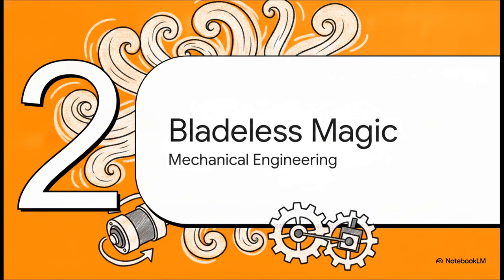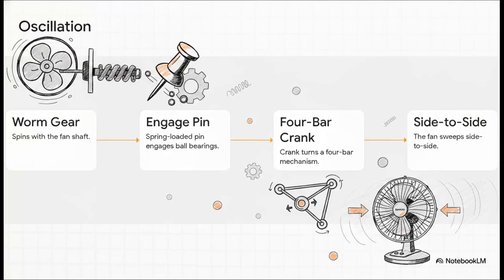Moving right along to Section 2, Bladeless and Oscillating Magic, uncovering clever mechanical engineering. Okay, have you ever wondered how pushing down that one tiny pin on top of a fan suddenly makes it look left and right? It's like a mini mystery. Inside the gearbox, the fast-spinning fan shaft turns a worm gear. When you push that pin down, a spring forces these tiny ball bearings to engage with the gear system, which slows the rotation way down. This then turns a crank attached to what's called a 4-bar mechanism. By fixing just one short bar in place, the super fast-spinning motion of the motor is beautifully and mechanically converted into that slow, relaxing side-to-side sweeping motion.